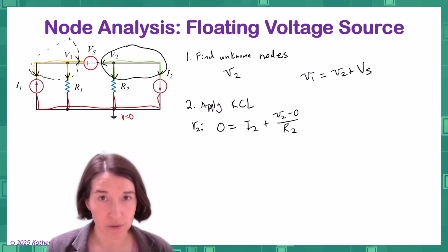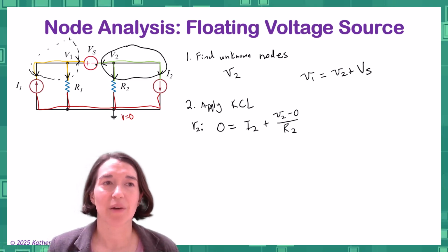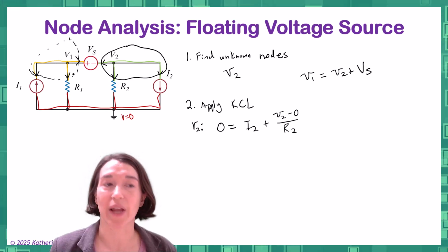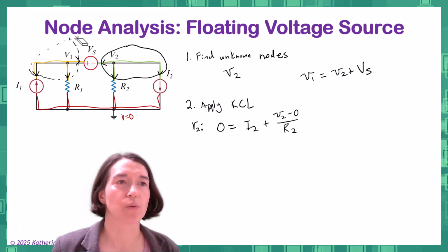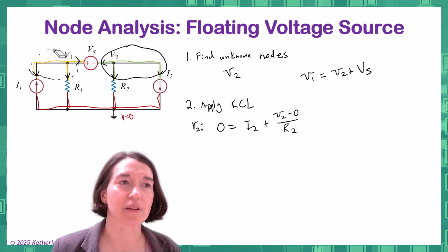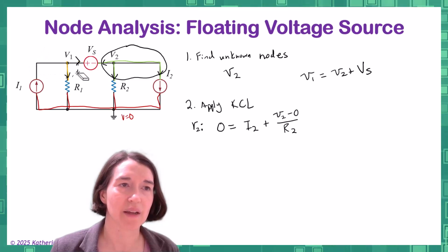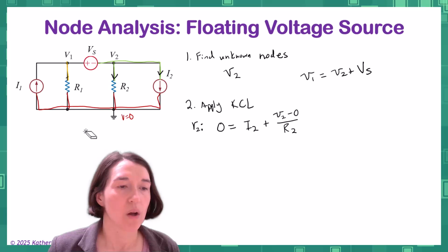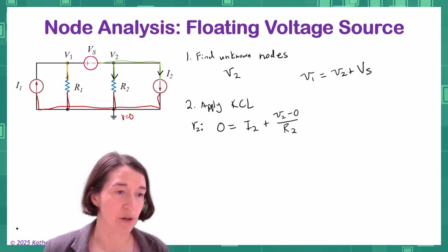So what can we do here? We can utilize the fact that the current coming in here has to be the same current, the sum of these two going out. Another way to say that is to draw a bigger circle, essentially. Sorry, guys, it's hard to erase all this. Okay, it's not beautiful. So instead of that smaller node, what we're going to do is a supernode.